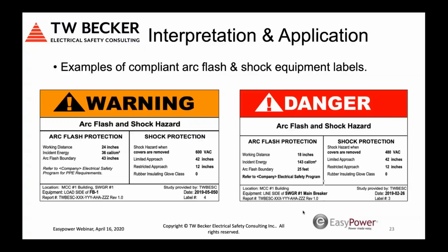Recently, unfortunately, I did review a report, and the warning labels, believe it or not, were provided with black warning on orange, red, blue, and green. That's where this information is provided to the end user, the client, and it further exacerbates and confuses the client's application of the information with their qualified electrical workers.